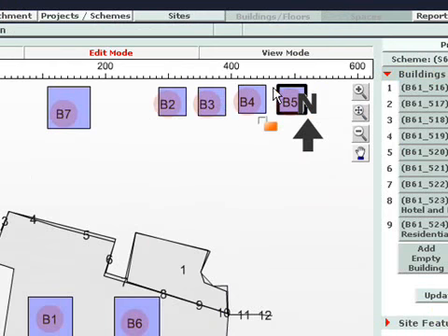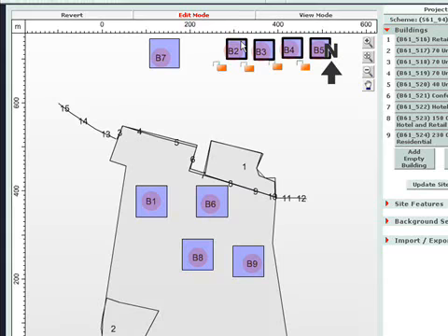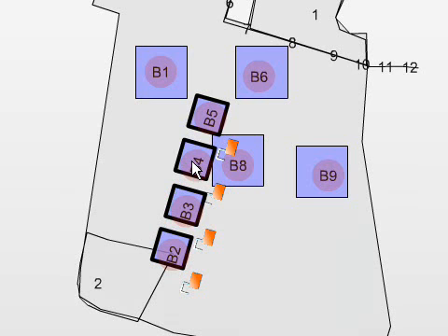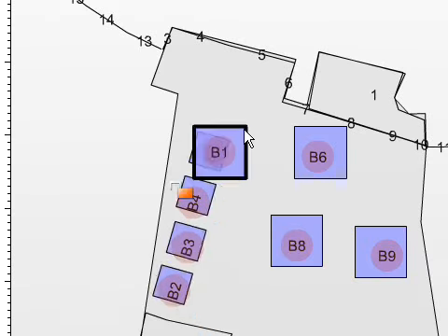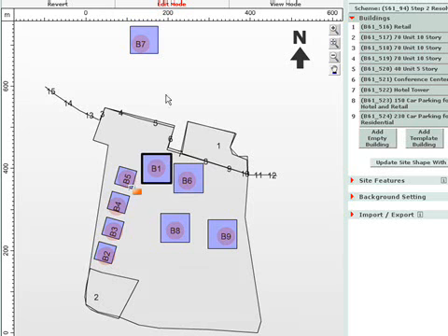Shift click selects multiple buildings. Drag. Rotate. The R is a rotate, so you can rotate the buildings. Continue to move them. So here's my first rough scheme inside Ops. It can be as rough or as precise as I'd like.